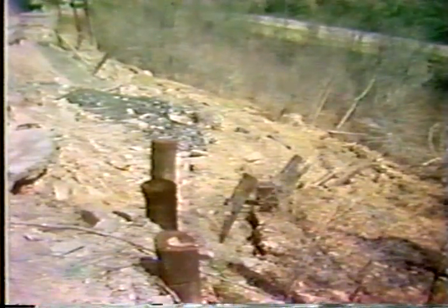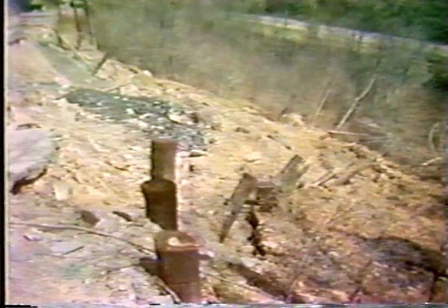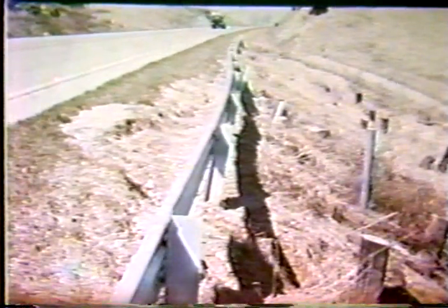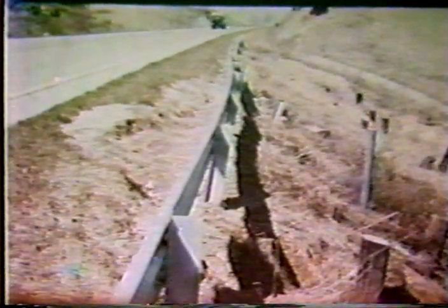Now let's look at some failures. No one likes to see a failure of any type, but these are cases where piles were very ineffective. They were driven in. For example, here, and let me point out one thing about this particular slide. You see a sort of a casing, a blue casing sticking up. This is what Dave was talking about earlier, and this is something you should recognize if you're a maintenance person. That's a slope inclinometer, and that tubing has a torpedo that goes down into the tube, and what they use that for is to determine how deep the failure plane is. So if you're a maintenance person, look at that slide very closely, protect that for the geotechnical engineer.